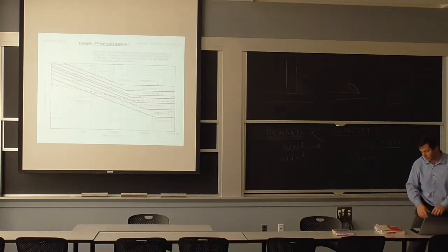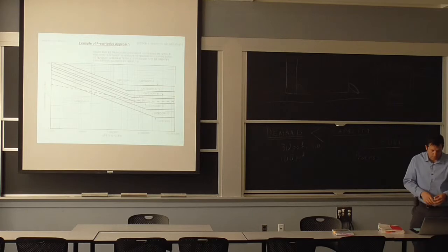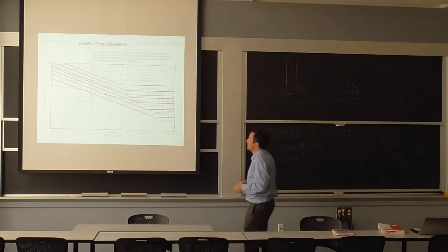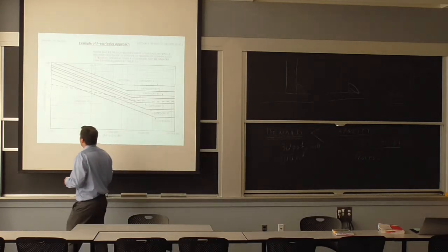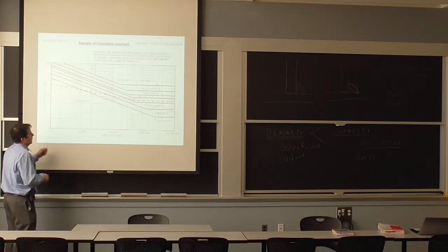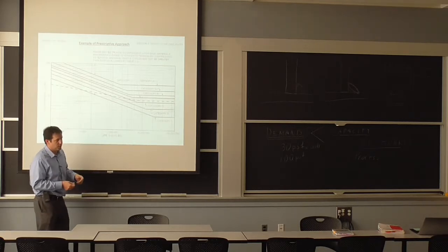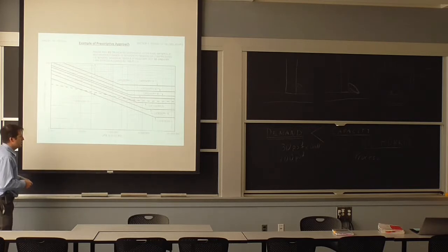For welding code, what they do is they take a base material, and this is the stress strain curve, the S-N curve that I mentioned earlier in the class, where this is the life. So as you go on and you have cycles of load, this could be a bridge or anything, automotive, aerospace components, something that has even poles for electrical transmission. You got some wind load on them, and they'll be subjected to that.